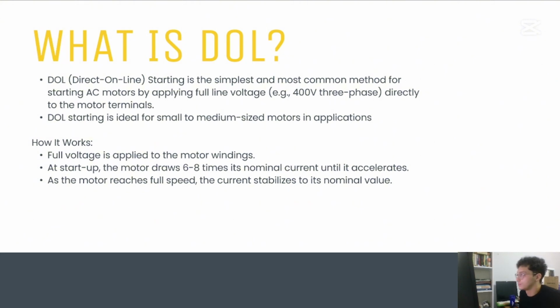What is DOL? DOL is direct online. Starting is the simplest and most common method for starting AC motors by applying full line voltage. For example, 400 volt three phases directly to the motor terminals. DOL starting is ideal for small to medium sized motors in applications.